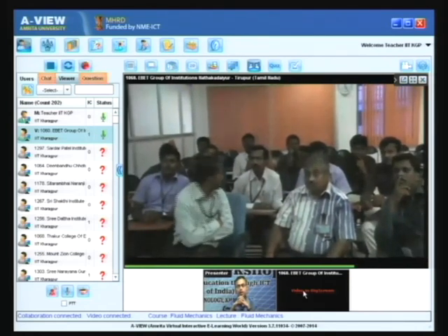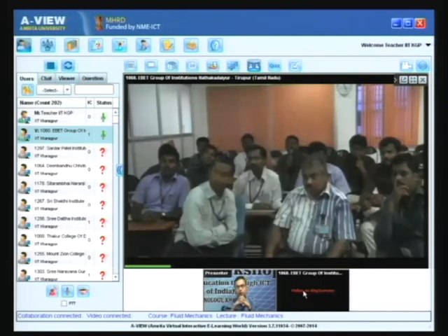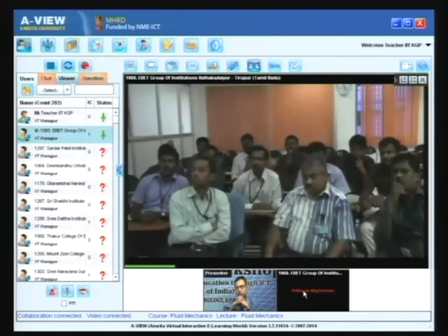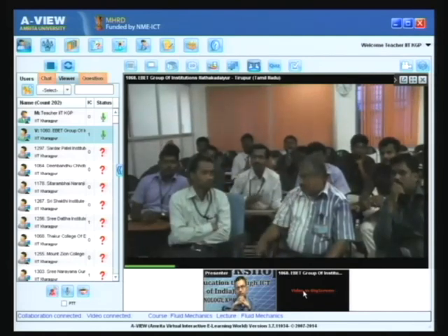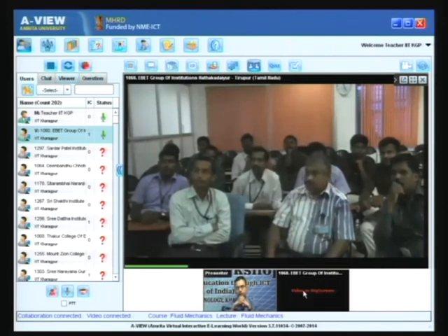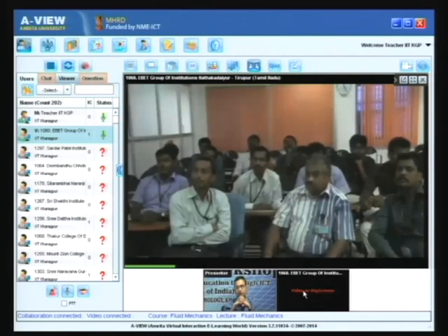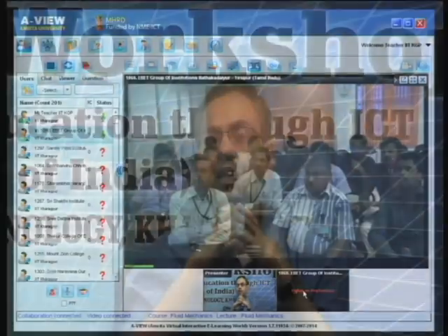Is area a vector quantity or a scalar quantity? Area, it depends on its representation. When you are talking about the stress, then you need to specify the orientation of the area. So, you specify it by the direction normal, and typically the outward normal of the area. In that representation the area is represented by the area times the unit vector in its outward normal direction, and that is called the area vector.